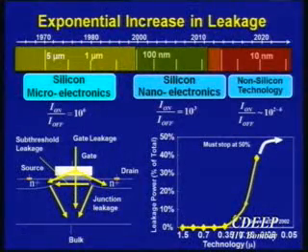But it turns out, again, the most important component of leakage current is actually the subthreshold component of current. And that's an exponential function of temperature. The other components that I talked about are the tunneling components, and the tunneling components are usually not a very strong function of temperature. I mean, there's a dependence on a few factors, but it's not a very, very strong function of temperature. So again, if you look at the active leakage, meaning when transistors are not doing anything, but in the active mode of operation, the leakage current increases, and it increases exponentially with temperature also. And that turns out to be the subthreshold component, which is the culprit for that.